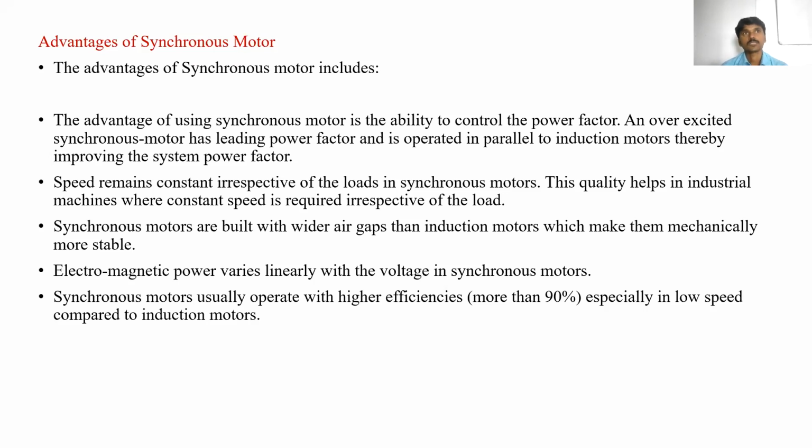Some industries require constant speed. Normally, if the load is applied, the speed decreases, and if the load decreases, the speed increases. But some industries require constant speed irrespective of the load, whether the load increases or decreases, whatever the load, the speed should be constant. In those places, we can use a synchronous motor.